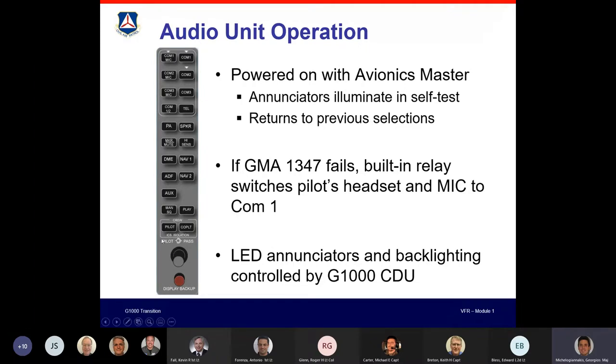And then we have the isolation buttons. Those are fun. Can anybody tell me what those do? Yeah, they let you control the intercom. So there's 3 modes. It's either everyone talking when neither is enabled, you can isolate the pilot from the rest of the passengers and the co-pilot, you can isolate the co-pilot from the pilot and the rest of the passengers, or if you hit both, then you isolate the crew, the pilot and the co-pilot, from the passengers. That's exactly right.